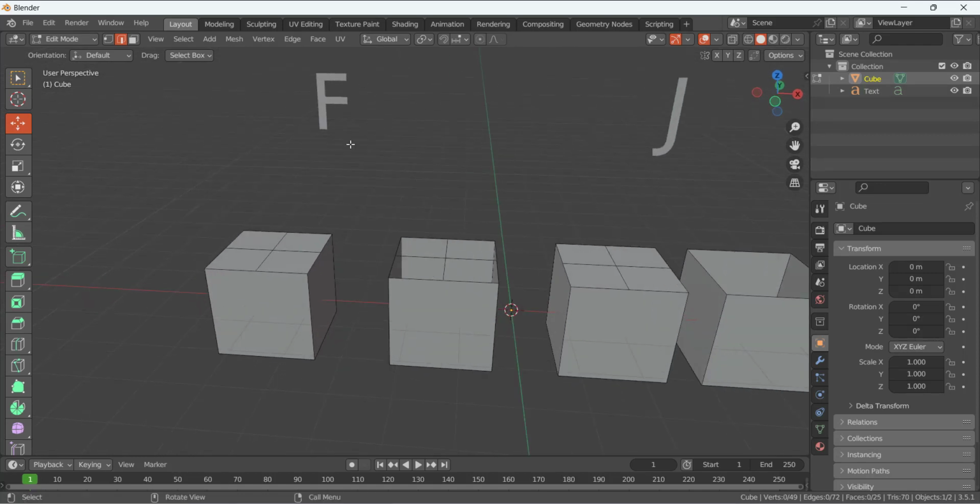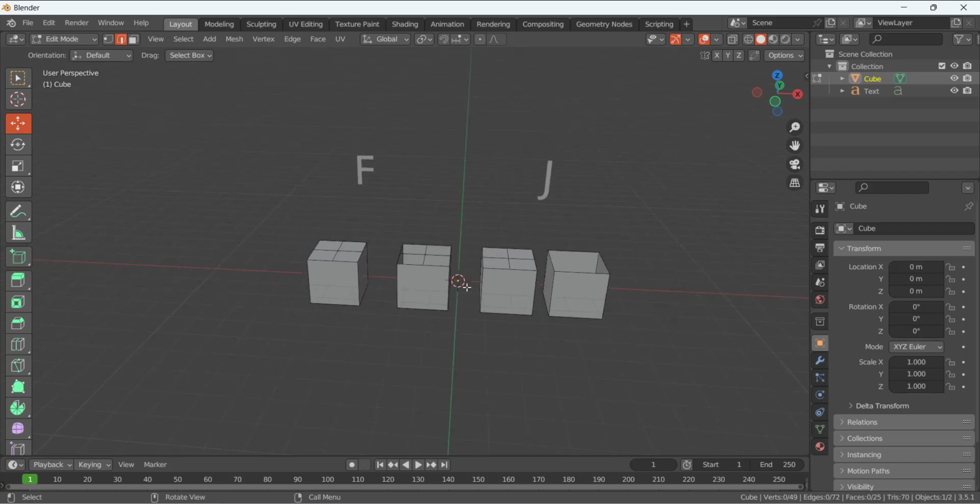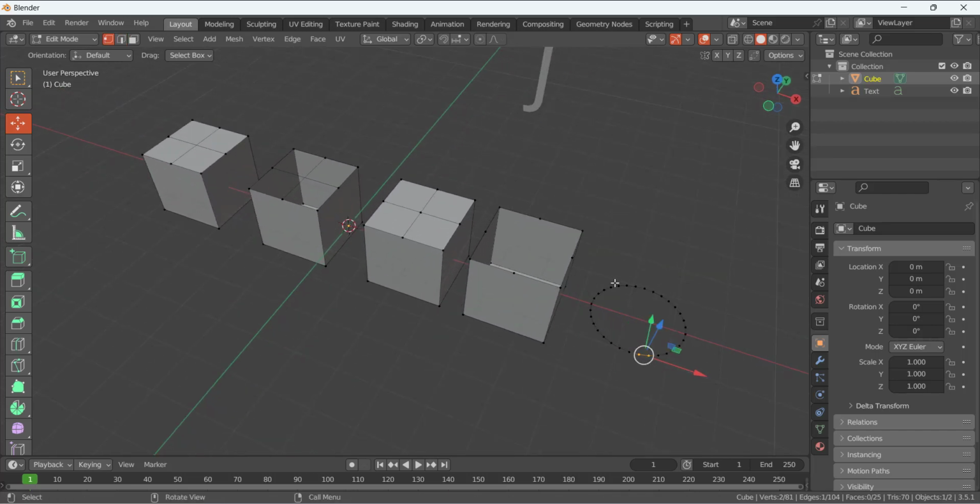And for the fill, you just remember that it joins the vertices, but it will not cut through it. For the join, it will connect the two vertices or edges, but it will cut. And one thing more, Shift A, if I am going to add a circle here at this point, and go to vertex selection mode, and here if I select this one and this one and press join, J, it will not work.